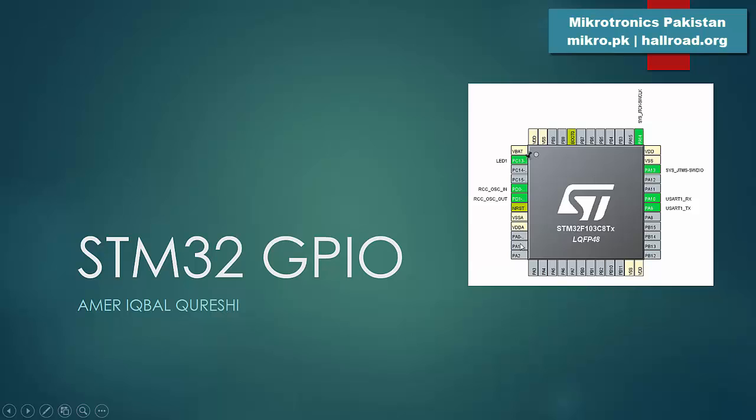GPIO stands for General Purpose Input and Output digital pins. We will talk about these pins later on. And actually, these pins have multiple functions as well, not only that these are for general purpose digital input and output. Some pins have serial communication with them. Some pins have I2C communication. Some pins are for analog to digital conversion. So these pins tend to have multiple functions, and you can select one of the functions at a time, and that is all configurable within the microcontroller.